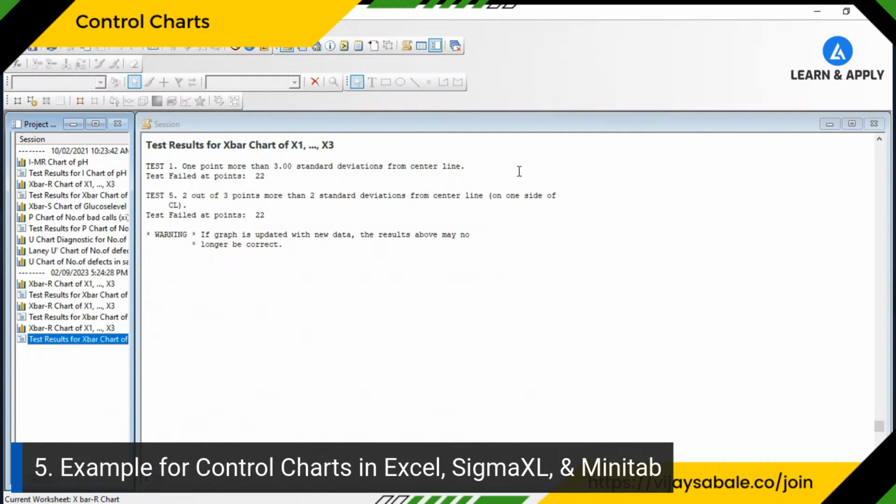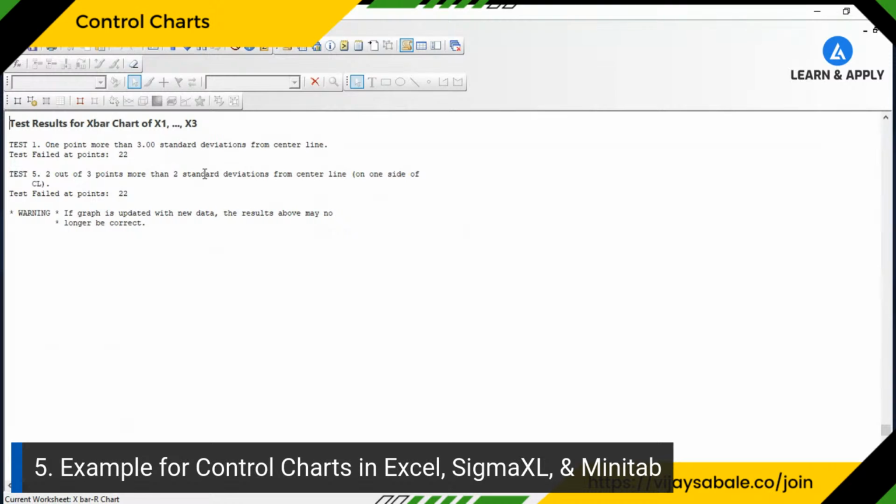1 point more than 3 standard deviations from the center line and 2 out of 3 points more than 2 standard deviations from the center line. So both of these are indicating that there is a larger shift in your process. So we need to take action on this so that we can control our process. We can remove the presence of special cause. Right? So this is the methodology that we can use in Minitab to draw this X bar R control chart.